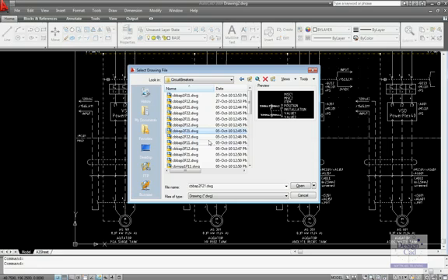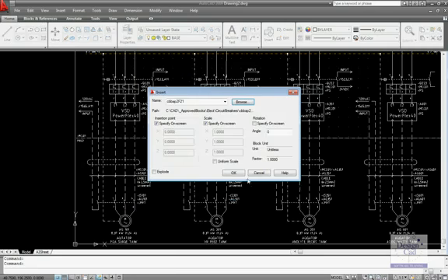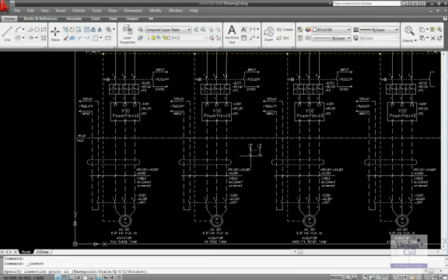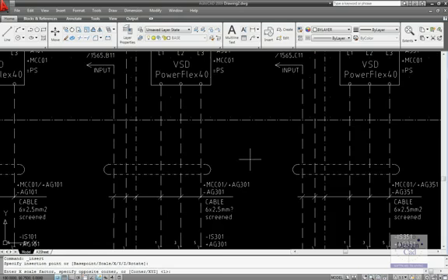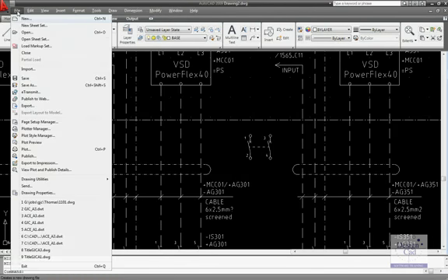You will notice that when we select the block here, we see the attributes associated with that block. So let's open up that particular one and bring it in, and we'll pop it down on the grid in that position. If you do it this way, you will be asked for the attributes that are associated with that particular symbol. So we've given you a detailed symbol library, and as I mentioned, if you were unsure of the name of the block, there's a consistent naming structure, and details of that are on the reference support website.